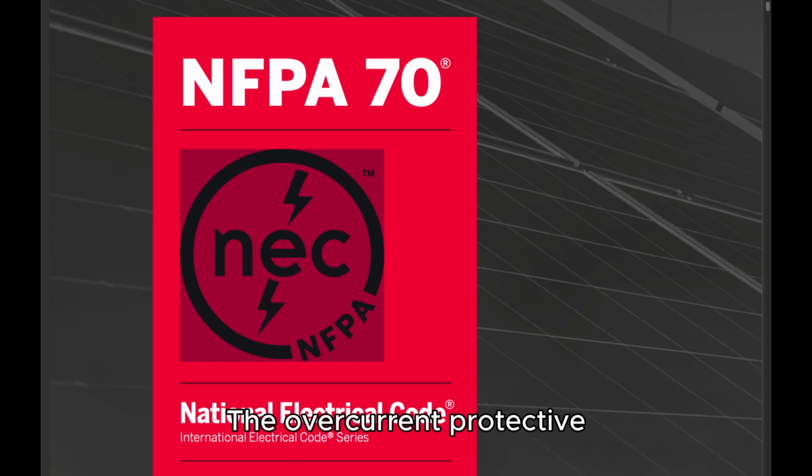The overcurrent protective devices, the total impedance, the equipment short-circuit current ratings, and other characteristics of the circuit to be protected shall be selected and coordinated to permit the circuit protective devices used to clear a fault to do so without extensive damage to the electrical equipment of the circuit.